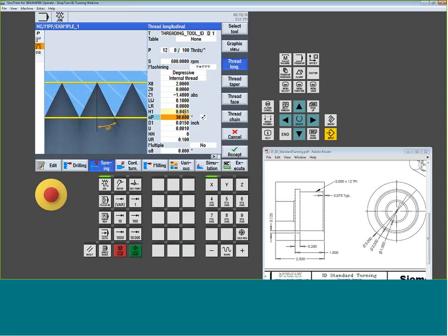My in-feed angle. Now with in-feed angle, make sure you toggle it from DP to the angle P value, because DP is going to be looking for a physical linear distance. It's much easier to just use half of the insert angle, which in this case would be 30 because I have a 60-degree insert.